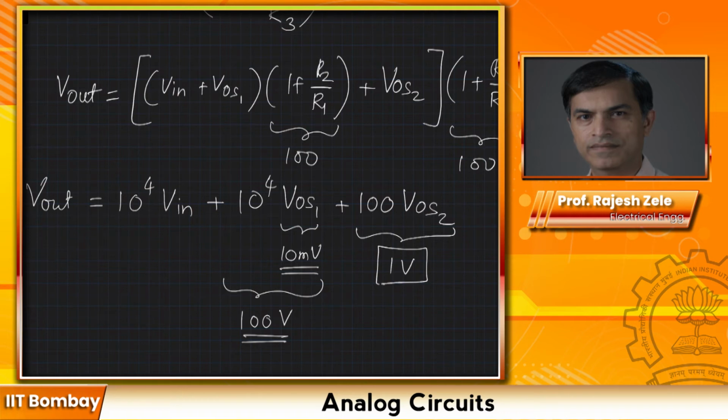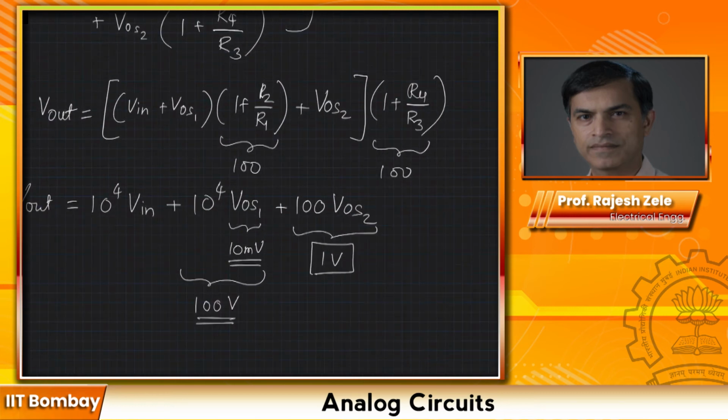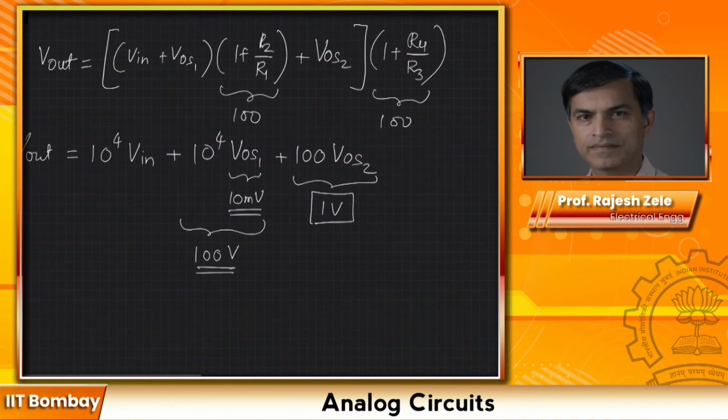And so when you buy an op-amp, just like the example I gave you earlier, how do we get rid of this offset, first of all? So what you can do is there is something called trimming of the amplifier. So this offset can be trimmed manually, and each manufacturer will provide you some circuit which is telling you that, hey, you go in there and you put a trim pot and you zero out each amplifier's offset. You can do that, okay? But that's a manual process.